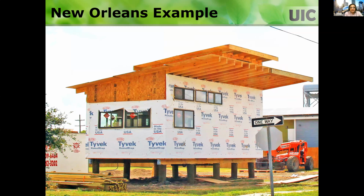As a geotechnical engineer, you should also look at foundations, right? So this is New Orleans. They estimated how much the future floodwater is going to rise. So instead of putting the foundation at ground level, they elevated the foundation, elevated the whole building, so that when it floods, the height is above the flood level and the house does not get flooded. Again, this is what's going on right now, to think about these climate impacts, because we cannot reduce them. These are going to continue to happen.